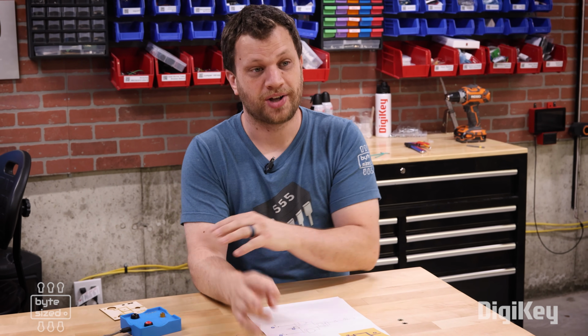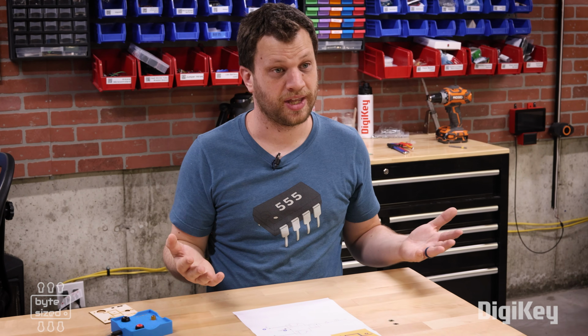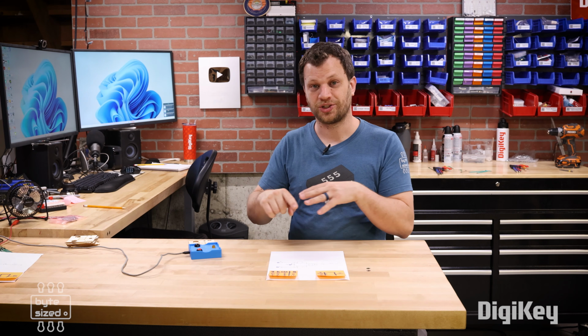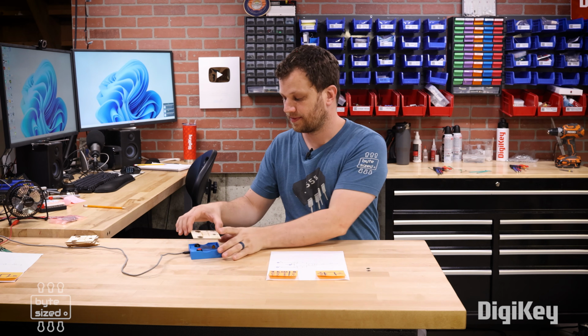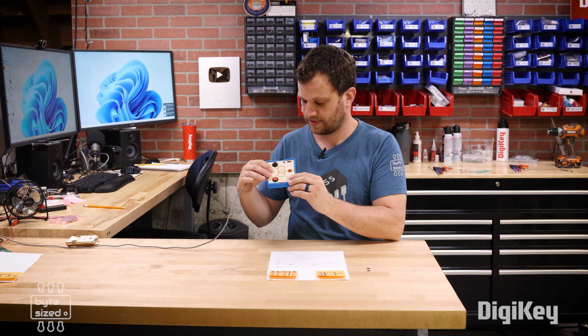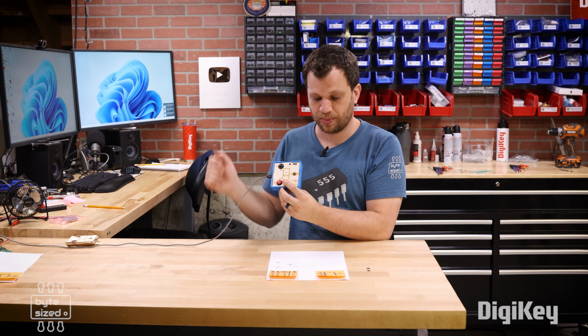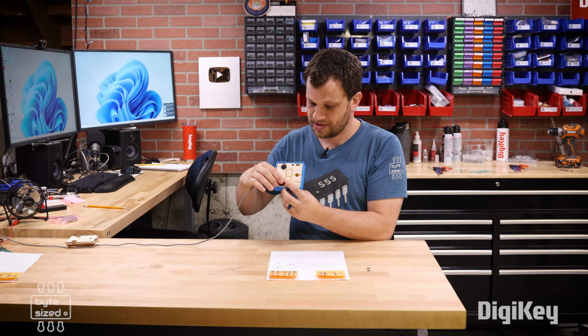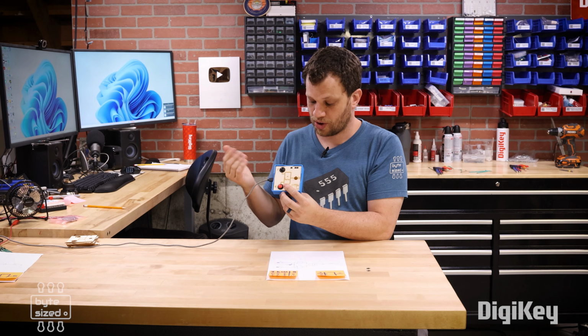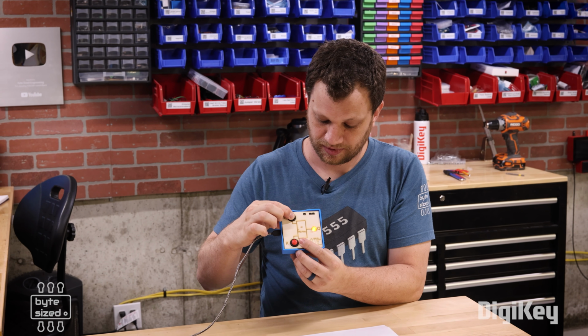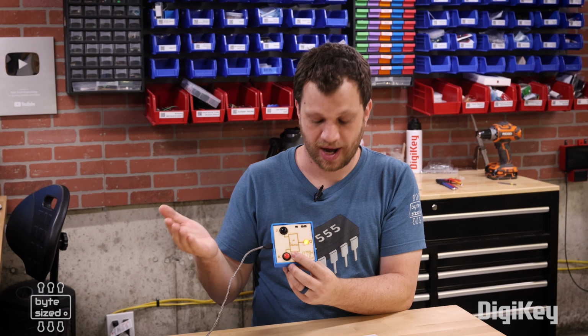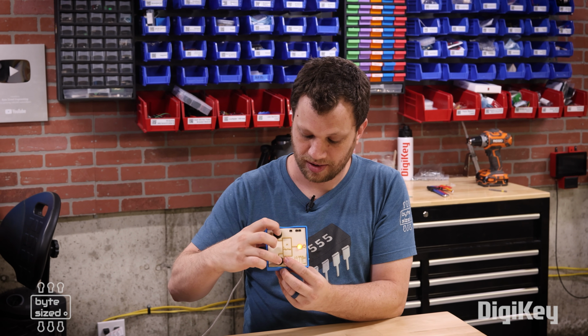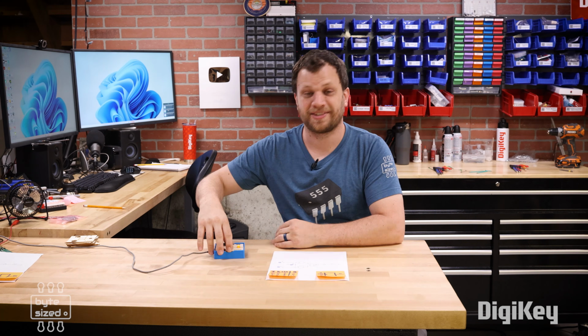So let's see what that looks like on the digital logic sandbox. The digital logic sandbox only has two buttons and we need a third thing to represent the clock signal. So I've generated a tone that turns on and off to simulate that rising edge of the clock. So when I put this tile on, you'll hear a tone beep every 1 second. So 0, 0, our output is unchanged. 0, 1, we've got a 0 on the output. 1, 0, latches our output high, and then 1, 1 will toggle it on and off.